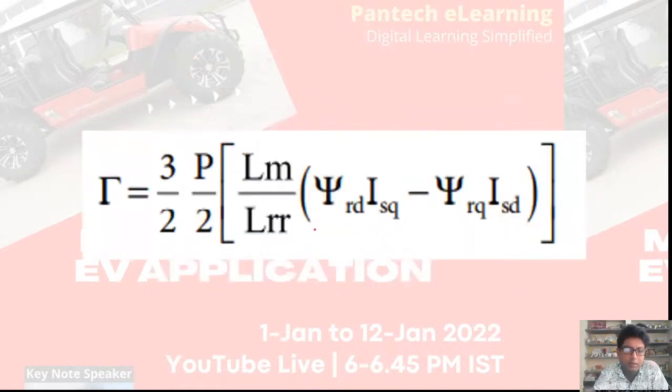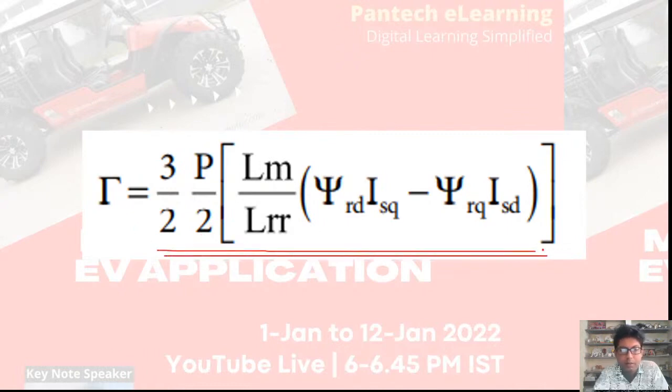Now I am coming to the torque equation. This we have already learned. We have established in detail how, from the rotational power, because torque is produced from the rotational power, by taking the rotational voltage and multiplying with the corresponding currents, we obtain the total rotational power. The power is basically the product of torque and angular speed, so if you divide by the angular speed, you will get this equation. So this is the instantaneous torque equation. These sets of equations will be used to implement the vector control.